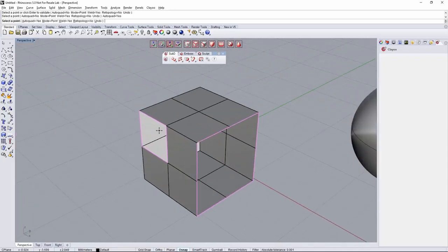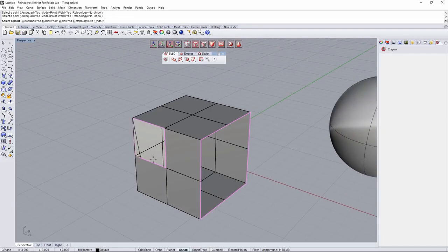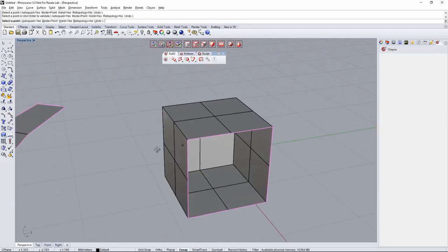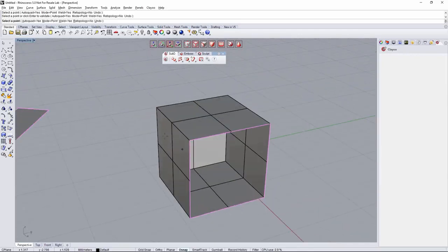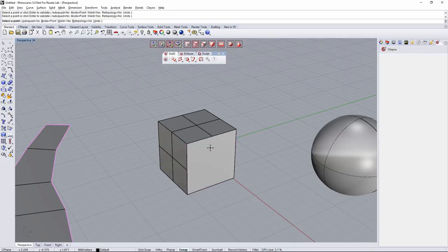So right now, let's fill this hole, so I can just create this face, clicking the 4 points. So it's perfectly fitting in there. Now let's close that with a single face, so let's click on AutoQuad, and we can just click all the times that I need to fill the hole and click on validate.